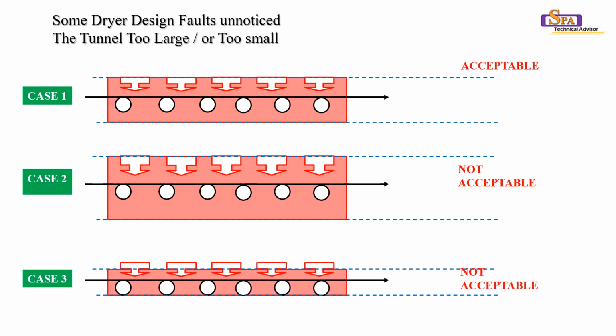Now case number 3, even this is also not acceptable. Here you will see that the tunnel size or the depth is too low. The idlers are practically touching the tunnel at the bottom, and this is also not acceptable.